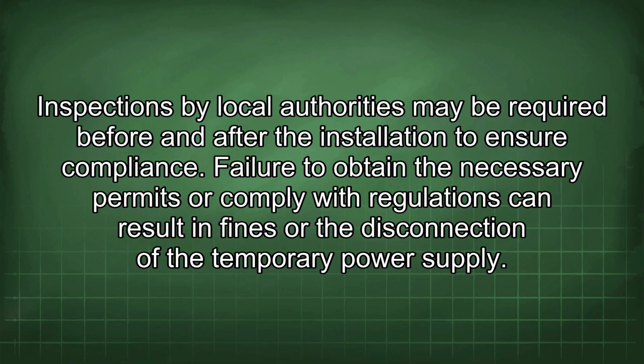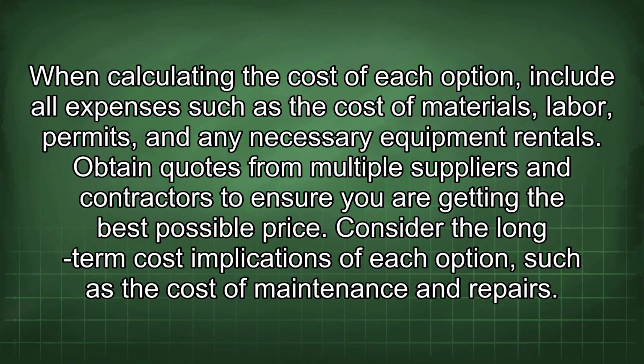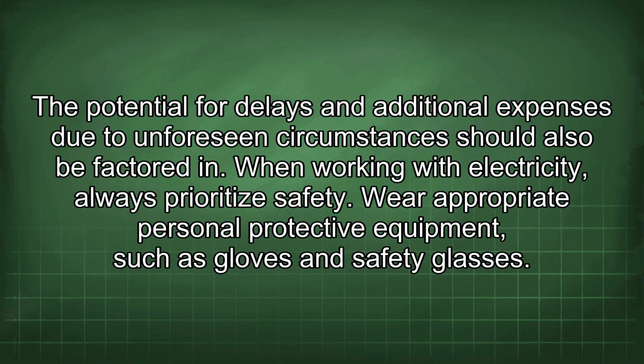When calculating the cost of each option, include all expenses such as the cost of materials, labor, permits, and any necessary equipment rentals. Obtain quotes from multiple suppliers and contractors to ensure you are getting the best possible price. Consider the long-term cost implications of each option, such as the cost of maintenance and repairs. The potential for delays and additional expenses due to unforeseen circumstances should also be factored in.